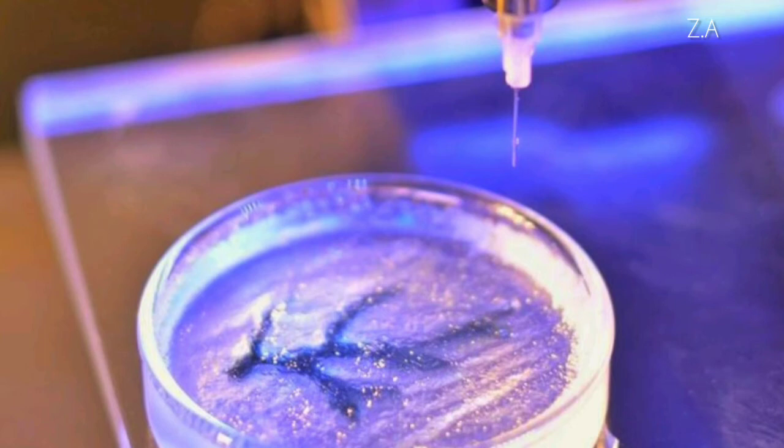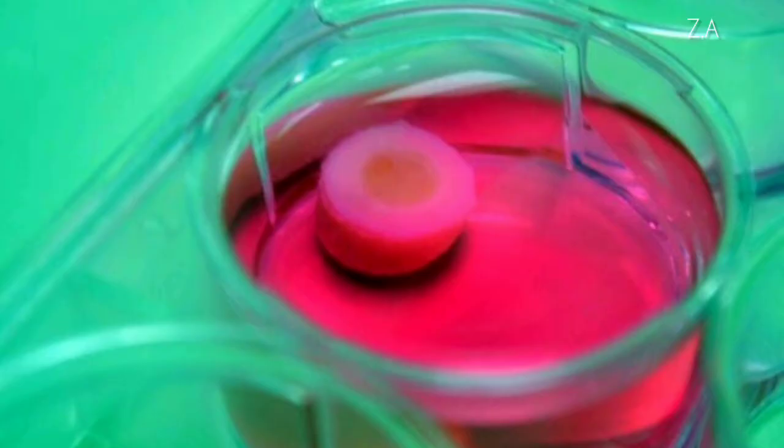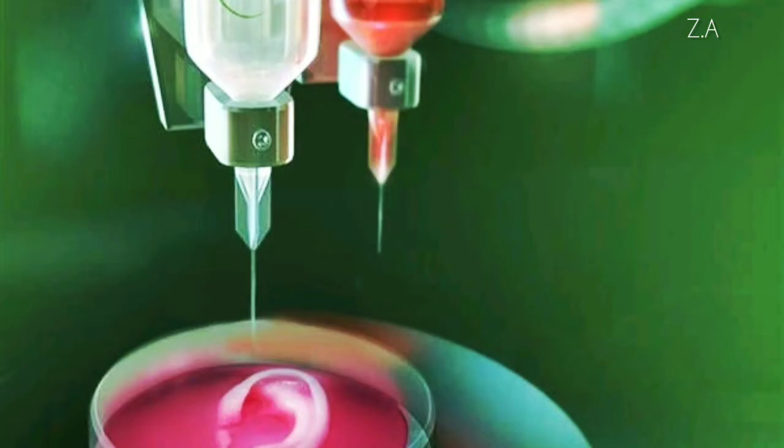The mixture comes out of the nozzle as a highly viscous fluid. In the step of solidification, as deposition takes place, the layer starts as a viscous liquid and solidifies to hold its shape. The process of blending and solidification is known as cross-linking and may be aided by UV light or specific chemicals.